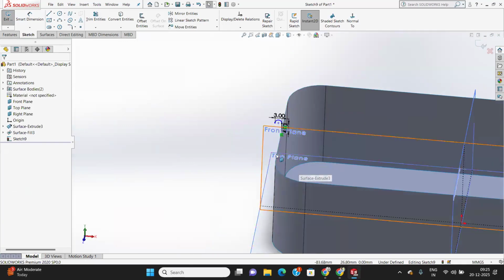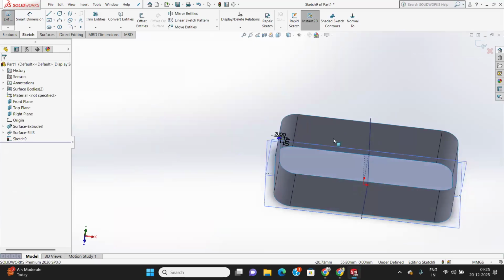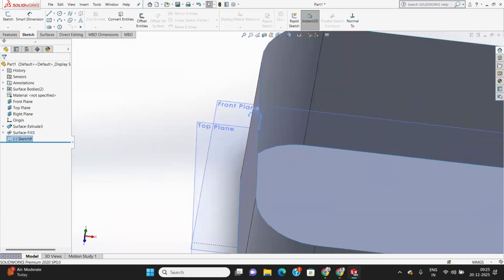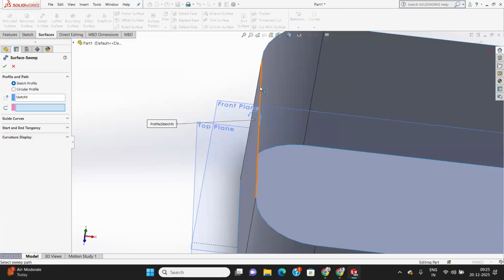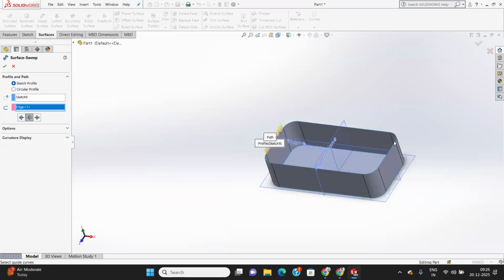This is your object that will be created right there. One thing also I want to do here. I want to sweep this path and this object. If I do the same thing using this space, I use a sweep. This is my object, and if I select this profile, then this will be swept on this portion only, not the other one. But I want to sweep this path in each and every portion, all the part.